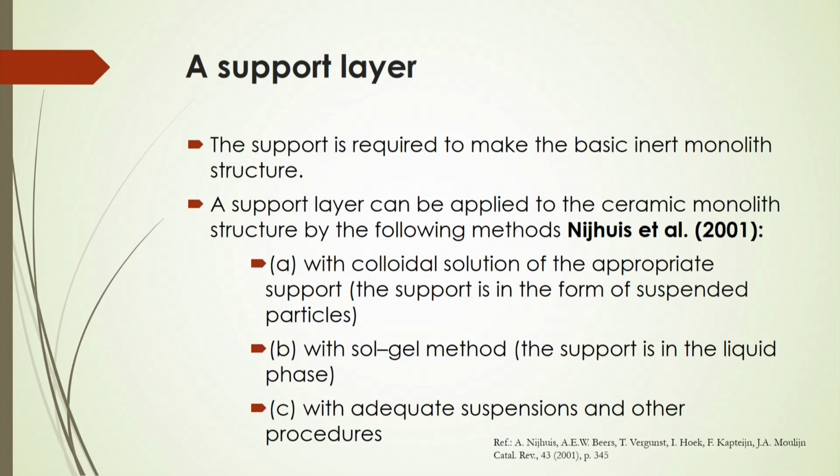Even with sol-gel methods, the support is in the liquid phase, and with adequate suspension and other procedures, it can also be applied to get the support layer on the ceramic monolithic structure by the following methods. So, that is why the support is required to make the basic inert monolith structure, and you have to follow a particular way to make this structure.